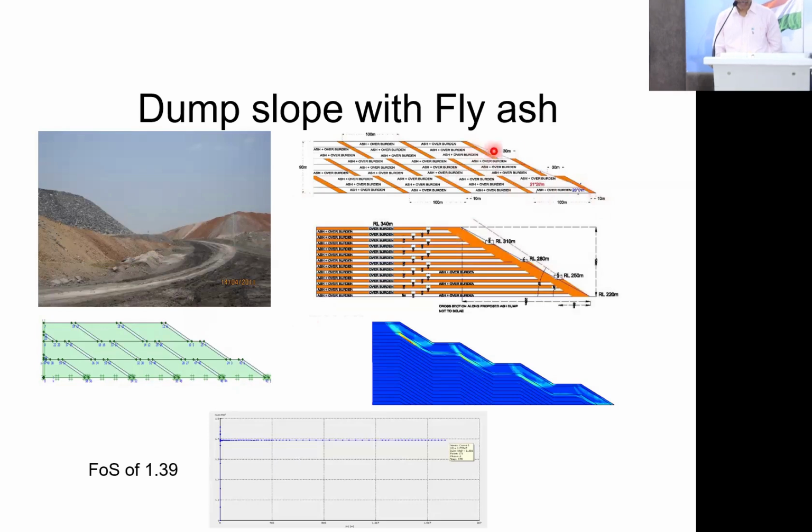That is exactly what I want to say. We did this one with a mining engineer, a gentleman. We tried different trials, then said this is how we can make it. After everything was done, DGMS also approved the factor of safety of 1.39. Environmental aspects were not that important at the time; we did it in 2011. Then they immediately said seepage will come, water will go out, fly ash is hazardous, so they said to monitor it.